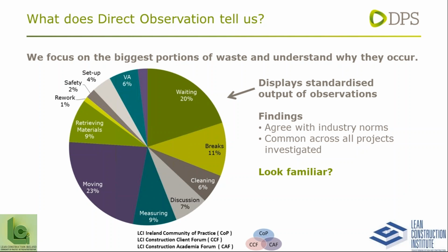Over a lot of observations that we've seen, it can take up to half an hour or 45 minutes of the day, every day, people sifting through tool trolleys to find the tool or the material that they need. So a simple 5S exercise, which is sort out what you have, understand what you need, get rid of what you don't need, and then put your tools that you use most frequently in the top drawers of your tool trolleys. Make a foam base for them so that they're sitting into something that they'll stay in all the time, so that when you go back, you know it's there the next time.